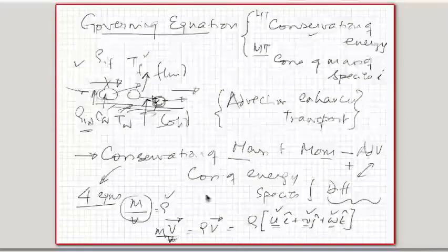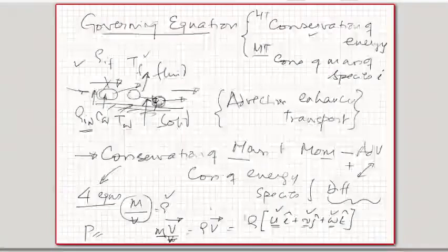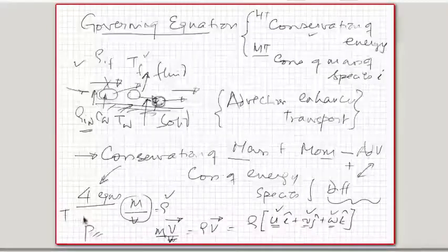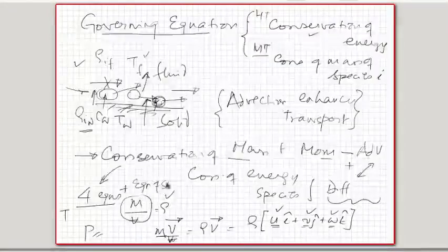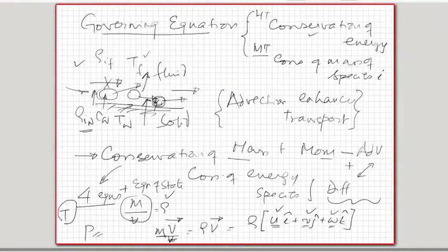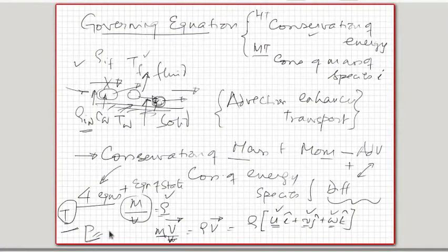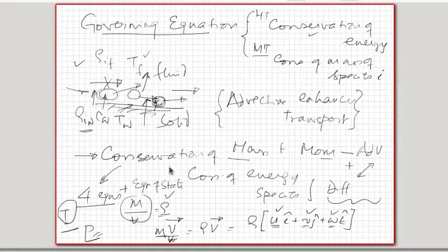And in addition to that, because there is also a pressure gradient that drives the flow, there would also be the variable called pressure, and there needs to be a relationship between the pressure, density and the temperature. So when it is isothermal flow, if there is a temperature T, then P, rho and T are connected through the equation of state. So plus the equation of state. But this equation of state actually connects the temperature. So when there is heat transfer, this temperature also varies, and therefore the density can vary as a function of temperature. The density can also vary as a function of pressure, and those things are matters of detail in fluid flow. When the density is a strong function of pressure, then we call it compressible flow, and when the density is a function of temperature and we need to account for the variation in density with temperature, it actually becomes natural convection flow driven by temperature differences.